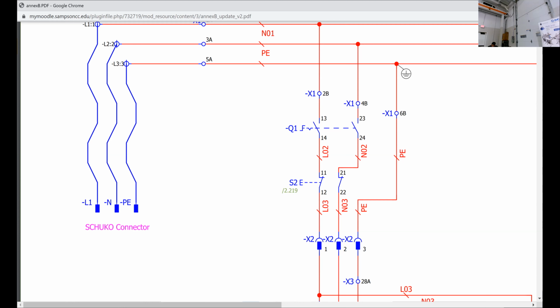There's only one location on the side. The symbol that shows those two contacts. Look, a double contact. We're talking about this symbol right here. I'm circling it. It includes two normally open contacts and an actuator, and the actuator is a locking detent that's a switch. And that's the international symbol for a switch.